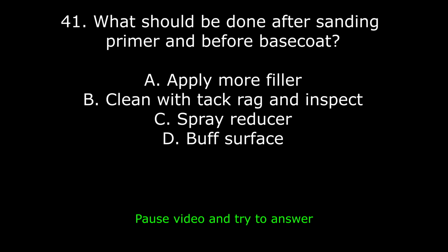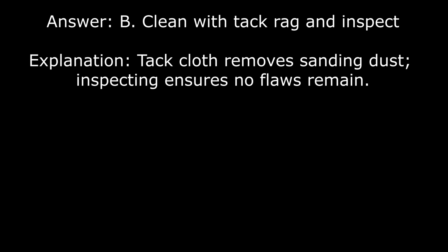41. What should be done after sanding primer and before base coat? A. Apply more filler. B. Clean with tack rag and inspect. C. Spray reducer. D. Buff surface. Answer B. Clean with tack rag and inspect. Explanation. Tack cloth removes sanding dust. Inspecting ensures no flaws remain.